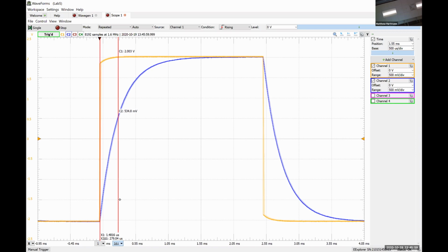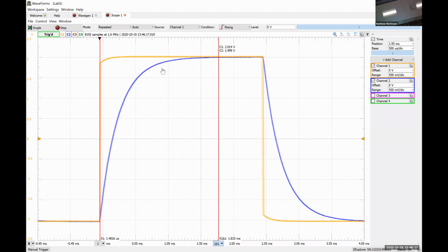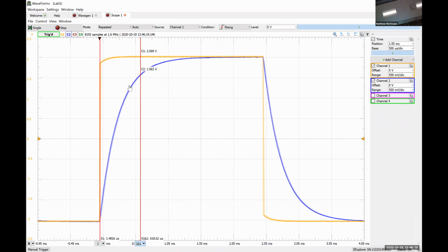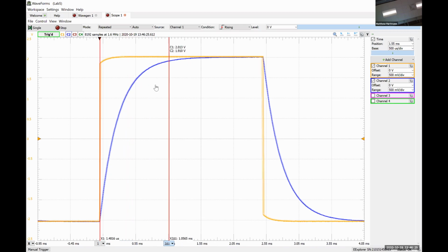0.528 volts, okay? So roughly 530 or so millivolts. The reason I say that is because that's what I was able to slide my scale over to. I put my leftmost marker at T equals 0, and I'm moving this right-hand marker to a point where, if you can see, channel 1, the voltage doesn't really change as I move over, because it's the top of that square wave. It shouldn't be changing a whole heck of a lot.